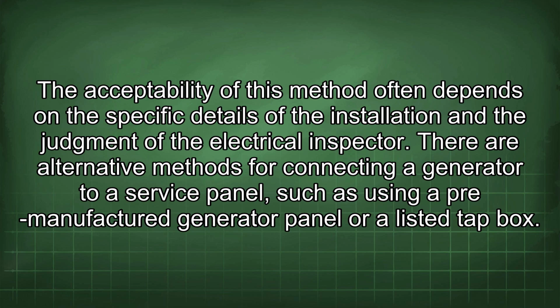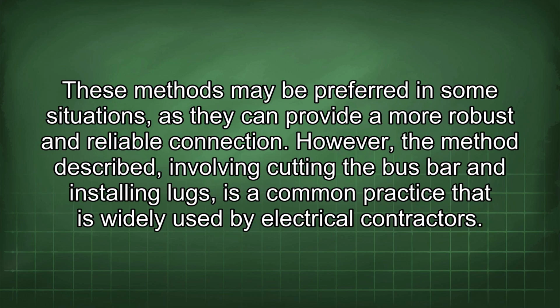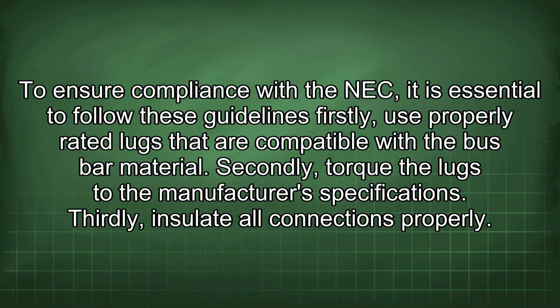or a listed tap box. These methods may be preferred in some situations, as they can provide a more robust and reliable connection. However, the method described, involving cutting the bus bar and installing lugs, is a common practice that is widely used by electrical contractors. To ensure compliance with the NEC, it is essential to follow these guidelines.